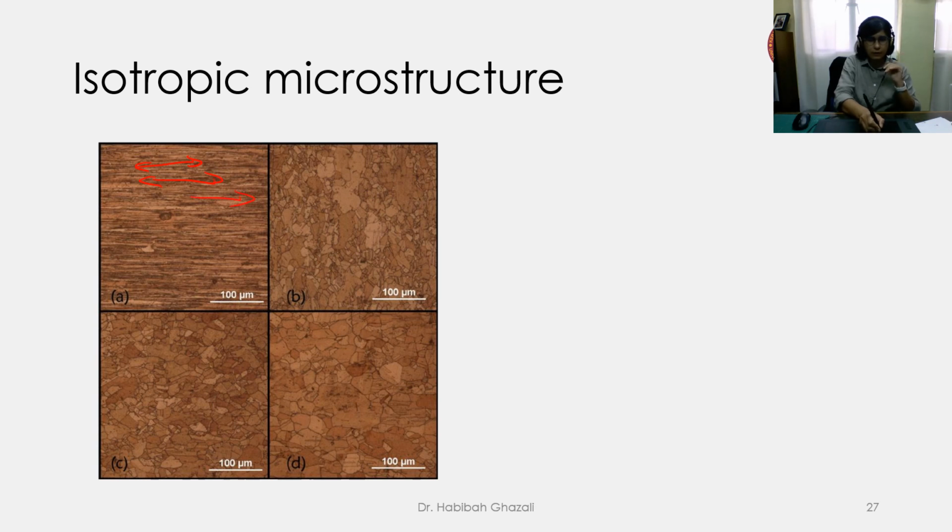this microstructure is very directional. It's elongated in this direction, but it becomes shorter in this direction. And as the material is heat treated, eventually you can see that the size and the grain shape change to equiaxed shape. So the dimensions of this shape are approximately the same in each of the directions. So they become an isotropic microstructure.